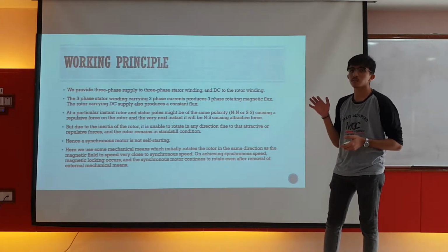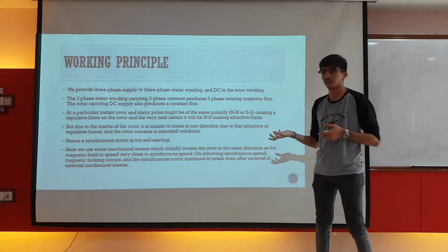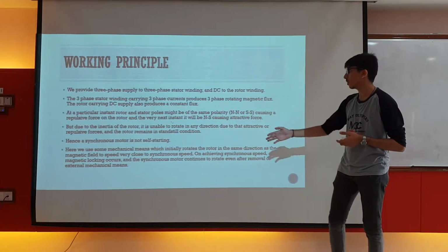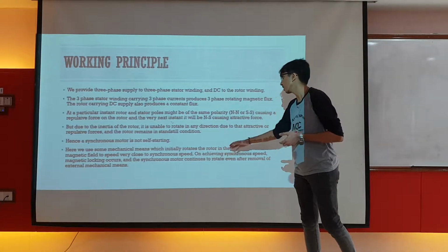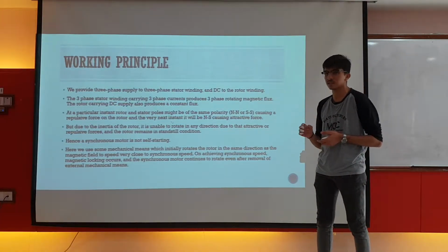So a synchronous motor is not a self-starting motor due to the repulsion and attraction of the poles. Here we use mechanical means which initially rotate the motor in the same direction as the magnetic field, at a speed very close to the synchronous speed.